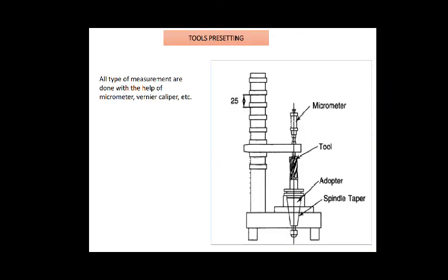Now further, one concept is preset tools. That is the setting of tools in advance, at a place away from the machine tool or offline, in special holders, known as preset tools. A presetting device is used to preset the axial and radial position of the tool tip on the tool holder. Once this is done, the tool holder is ready to be mounted on the machine and produce a known dimension. Presetting devices of various levels of sophistication are available.